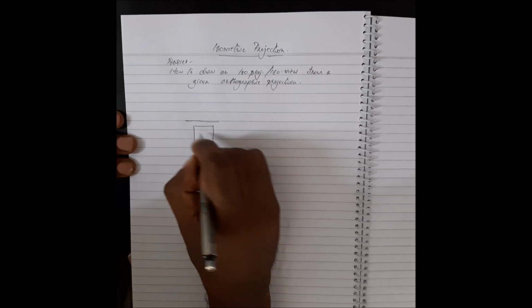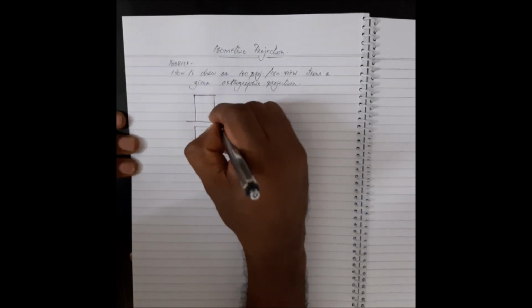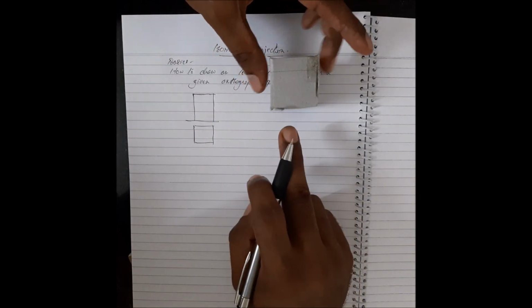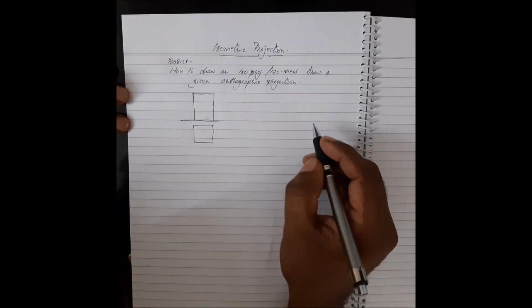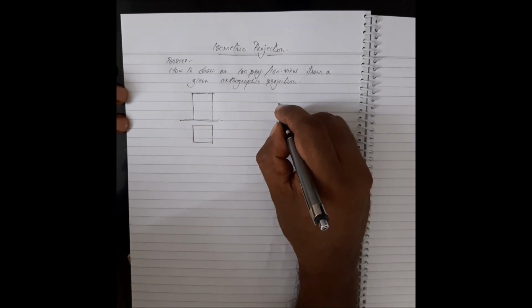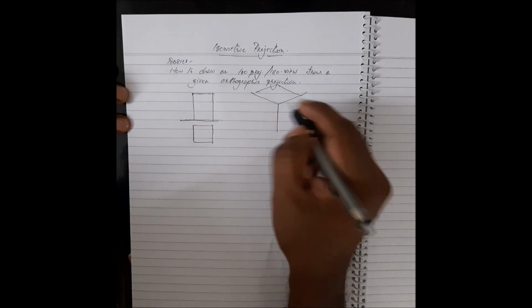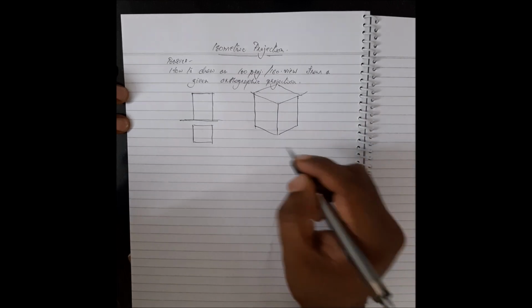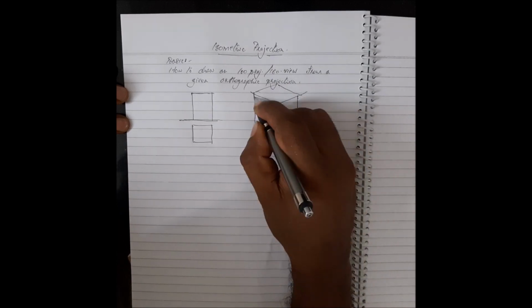and it always depends on the position of the solid. But let's say you have a square prism just like this, resting on HP on its base, so that in the top view you can see the square, in the front view you can see the rectangle. Right, just like this I've drawn here. Now if I draw the isometric projection of this, you get a figure like this. I'll just exaggerate a little bit so that you can see it. It's not the actual thing, but you'll get a figure like this if you draw the isometric projection.